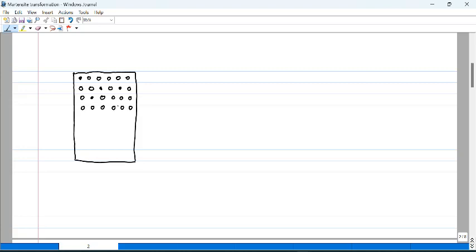Okay, so something like this, I am not going to draw all the atoms. So from here, you could understand the pattern in which the lattice is formed. For example, here if you see, there are 3 parent atoms and 1 solute atom, right? So that is the arrangement of atoms that you have in the parent phase, which could be the austenite in this case, if you are talking about austenite to ferrite or austenite to martensite.